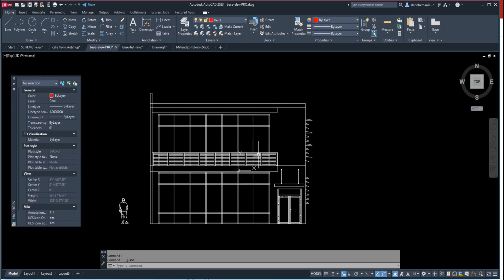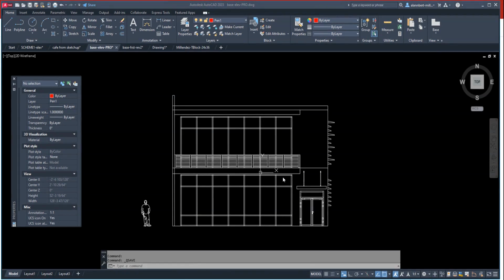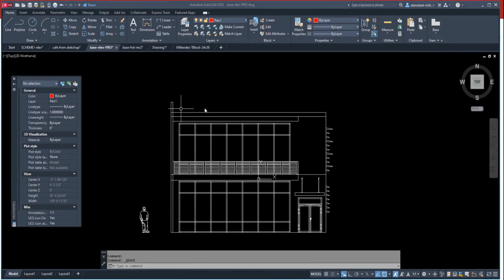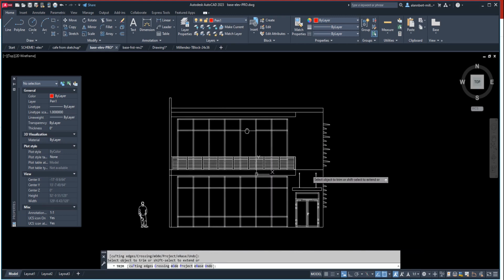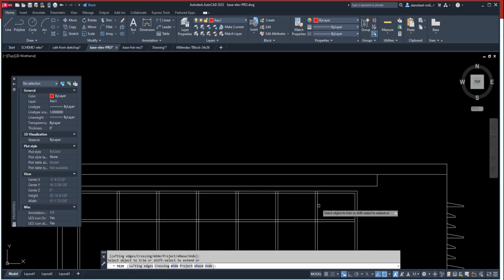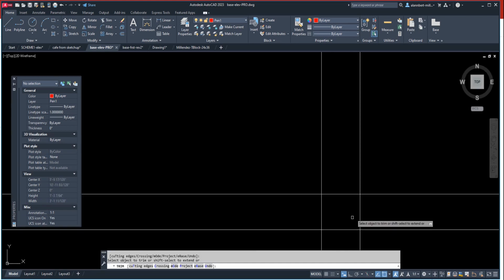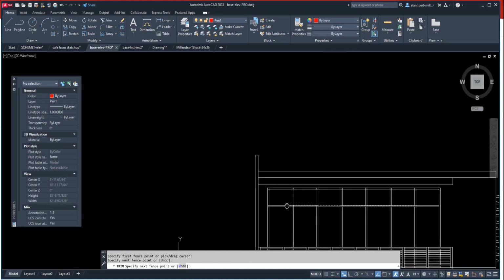And then you just have to clean this up. So that's what we're going to do next. To clean this up, we're going to simply use the pen colors that we're supposed to be using. Also, we don't need these double lines here, so we're going to just trim this off. Okay. What else? Sometimes you don't like stuff like this, and you want to trim off the frames just to make them clear. We can do a fence, and we can just click all the way here to the end.